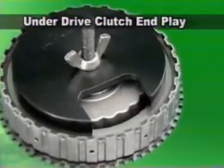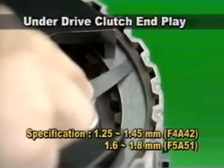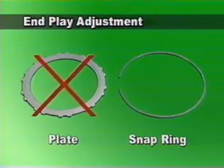Since the wave-type discs are applied to the underdrive clutch and overdrive clutch, measure the end play with a thickness gauge after installing the spring compressor. When it is over the specification, adjust the end play of all clutches except brake by snap ring. Select a snap ring from 15 kinds of thickness and replace it.